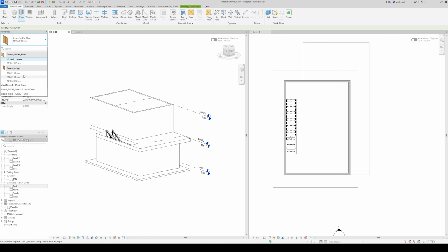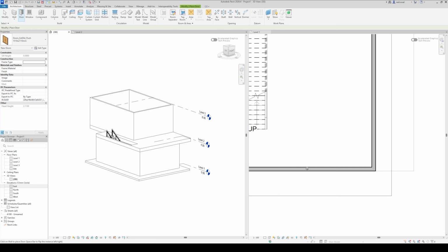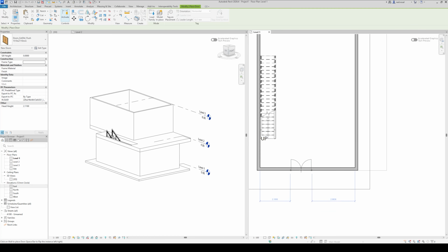I can choose any type of door that I want. I'm not too sure if you guys have these families at your end, but maybe later in this tutorial I will show you how to access more door families, furniture, and all that. But I'm going to start maybe with a double door entrance for my main. I'm going to go to my level 1 plan. It's going to snap at the center over here. As you can see, its measurements: its center is at 2.54.